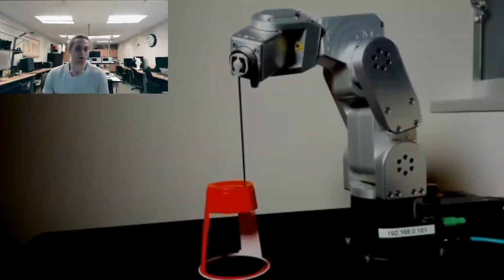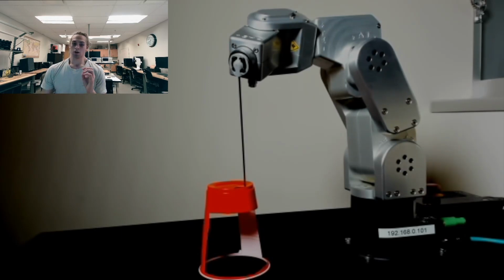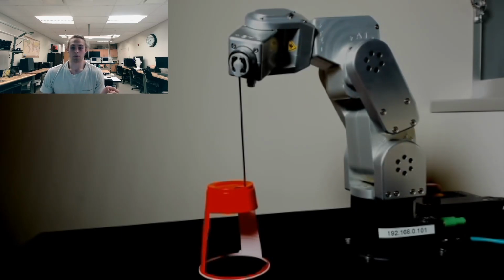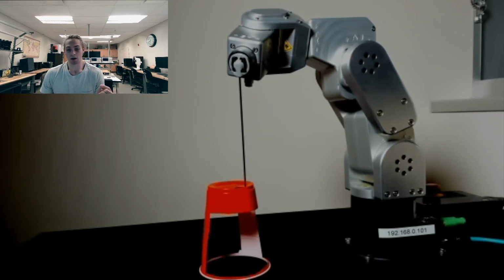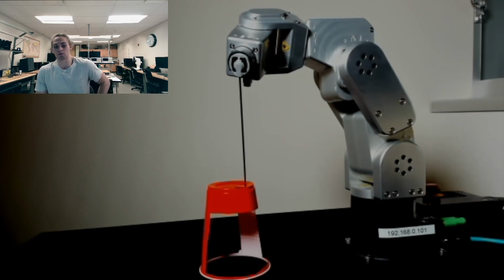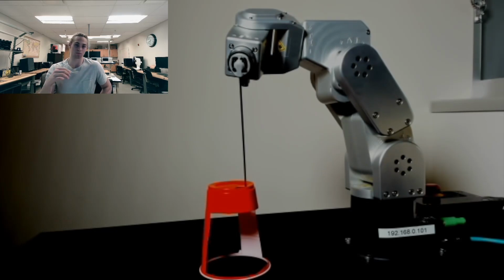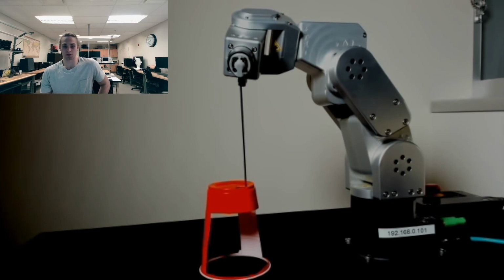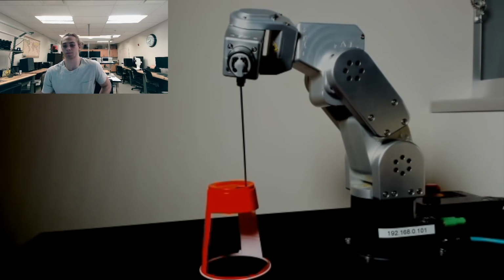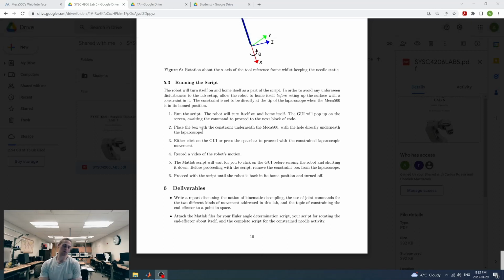Yeah, and the robot's still going through its stuff. So if it was confusing before at all, you've got the initial Euler angles of the robot once you're in here. And then you've got another set of Euler angles that is favorable for the first point that the robot's going to move to with the needle tip when it puts the needle deeper into the cup. So right now what you're doing is that rotation about theta. So once you've executed all of that, hopefully the robot does what it's supposed to through the hole in the cup.